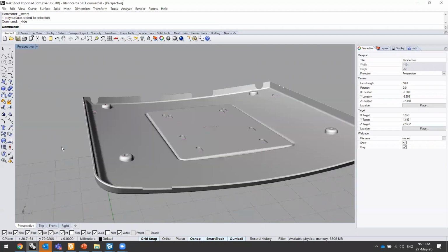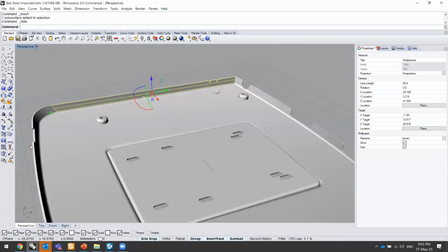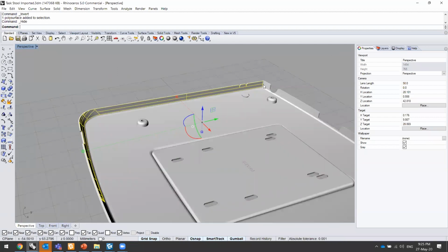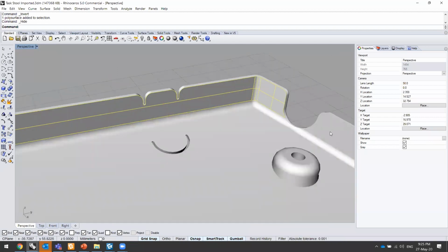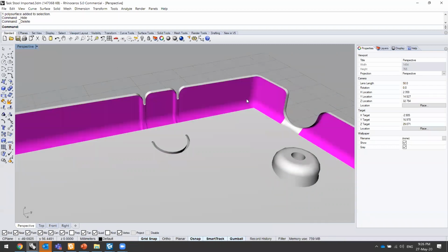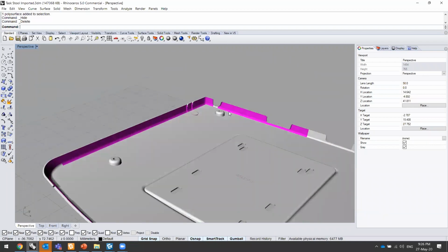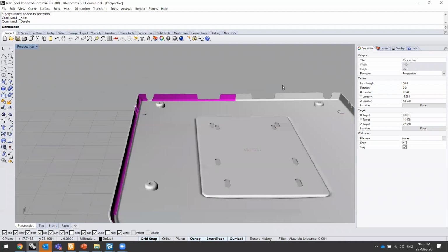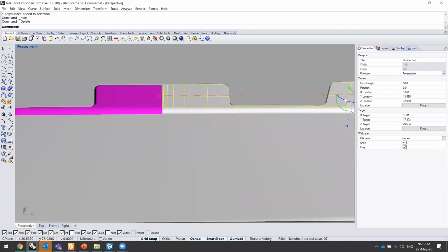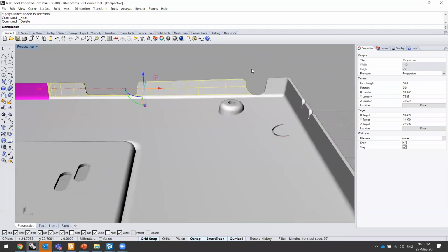And you'll notice the advantage of solid modeling is that all the surface information is still in place. So it's generally quite easy to select and remove them. But once you actually convert them into a mesh and bring it back to a CAD software, it's much more complicated. So there are advantages to working in a solid format.